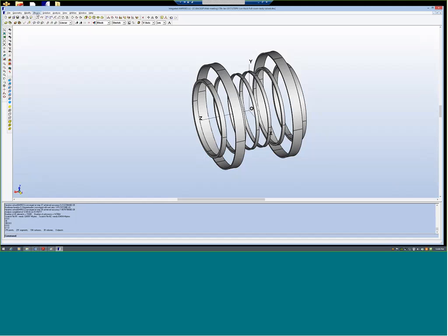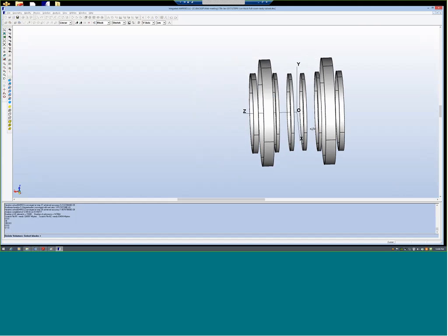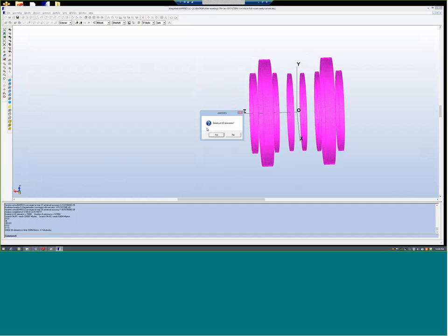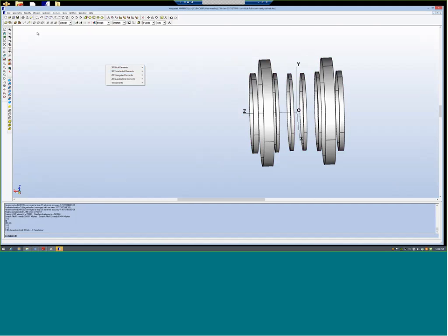Now modify, delete volume. Because at the z equals 0 plane it has a mirror symmetry, take this part out. Always do one thing before you delete it: delete the mesh first so that it will become faster. Delete all mesh. Also quadrilateral, delete all.